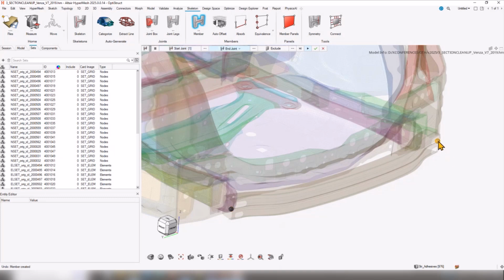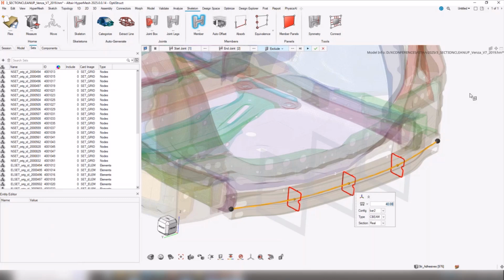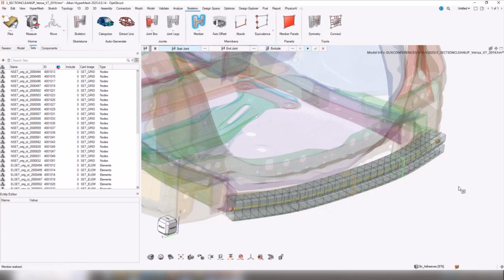Click joint 1, joint 2. This is going to be the preview, and this is going to take a little bit longer because we're doing the filtering interactively now with the centroid computation. You can now see that we have filtered out all the additional noise without changing the profile of the cut planes. And now when I click go, this is actually quicker now because it's processing less. And you can see now we've got a very clean output for that profile of that rear fender.